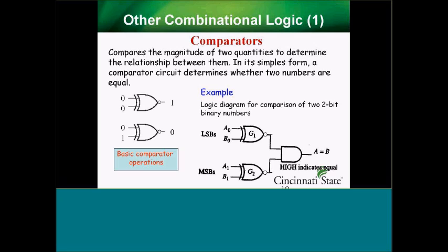I said, okay, well, if you think about it, look at the XNOR gate. This is again my trying to convince them that they really need to know all these gates. The XNOR is going to be 1 if both of the inputs are the same. So it's the opposite of an XOR, and it has a very good application in comparing two numbers. So you go bit by bit. If I have a multi-bit binary number, I just compare them bit by bit to see if they actually are the same.